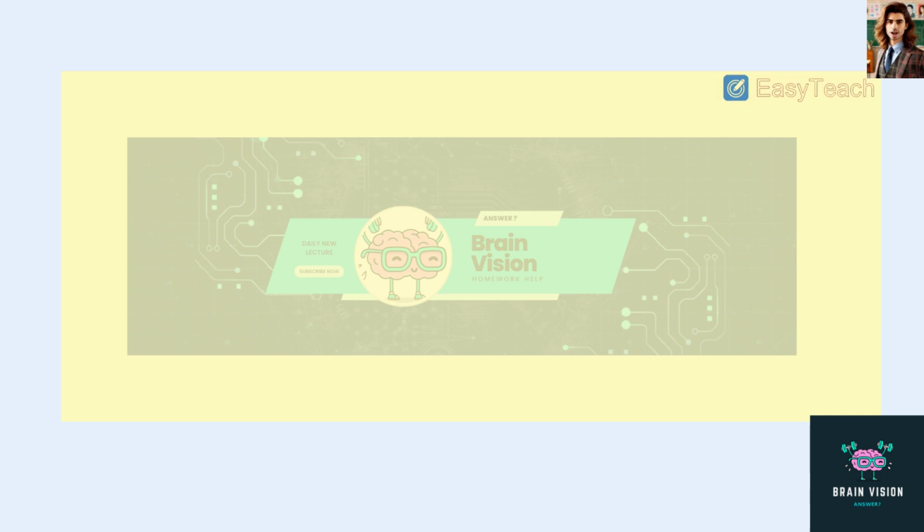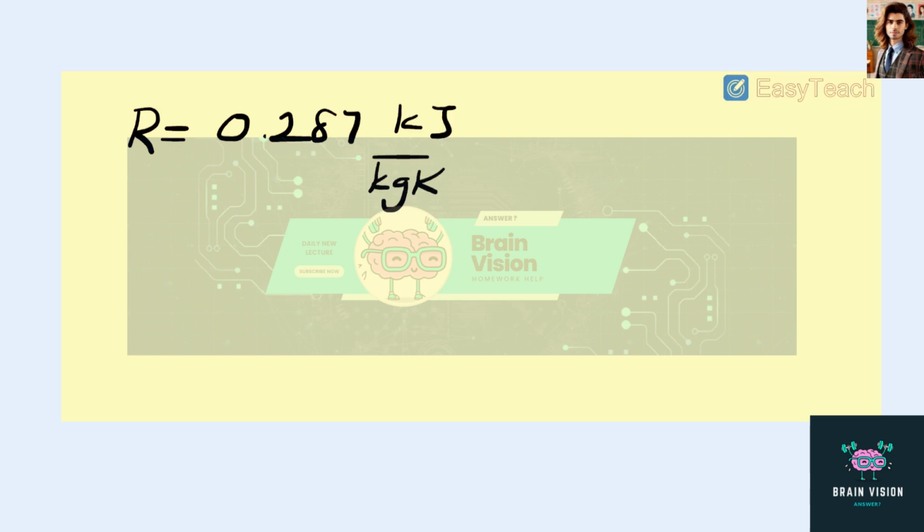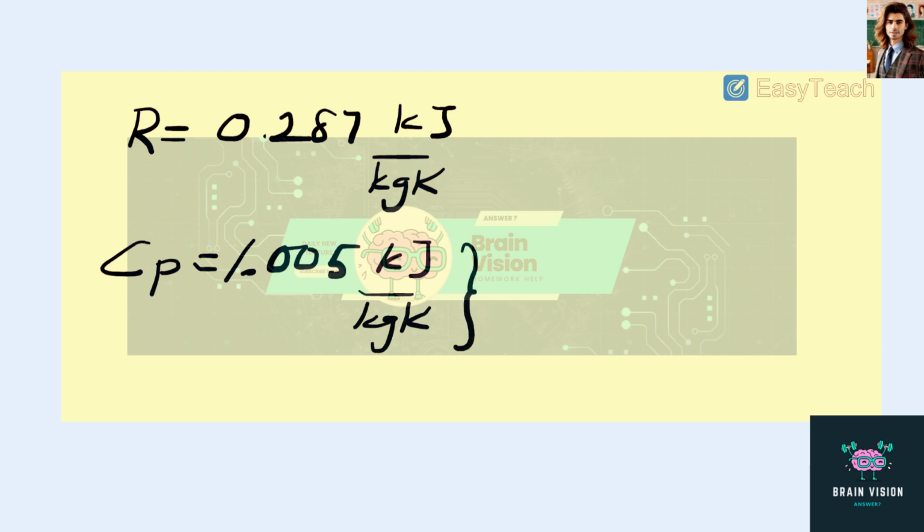So first thing we're going to do is go ahead and find the properties of our gas. We know our gas is air, so the gas constant is going to be 0.287 kilojoules per kilogram Kelvin. And we're also going to see that our specific heat for constant pressure, Cp, is going to be 1.005 kilojoules per kilogram Kelvin. And this is a quantity that pertains to the Cp at room temperature.